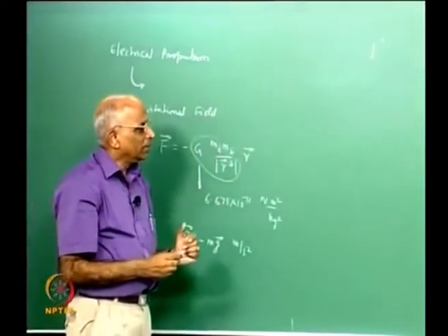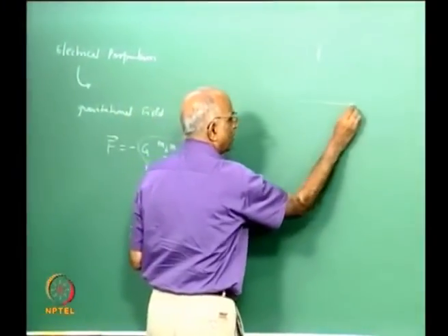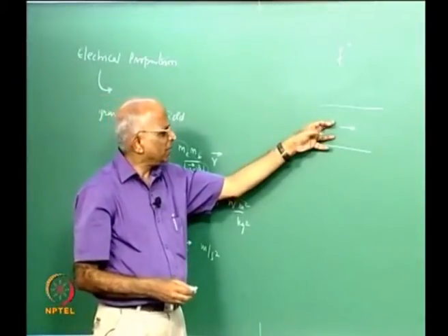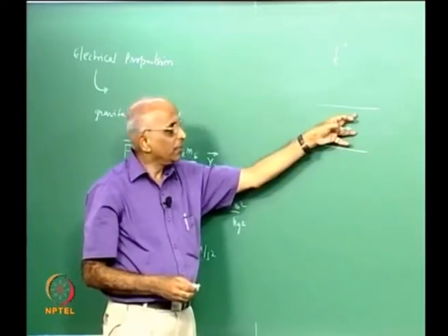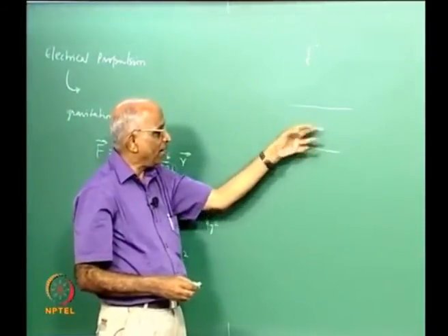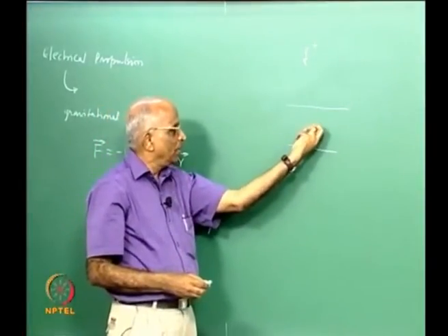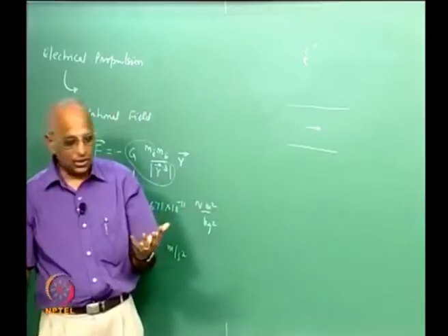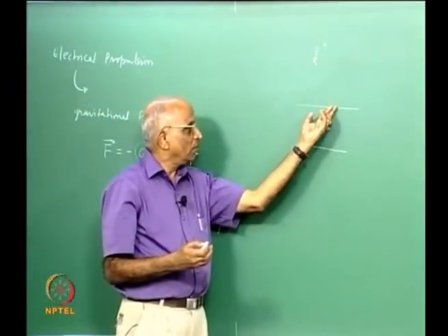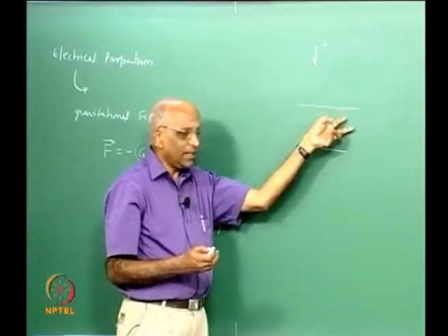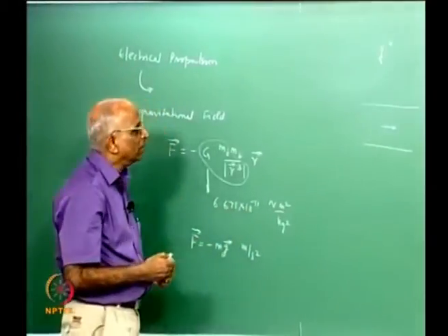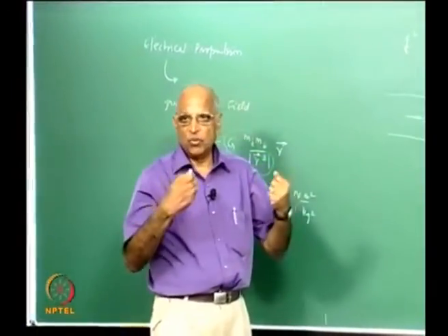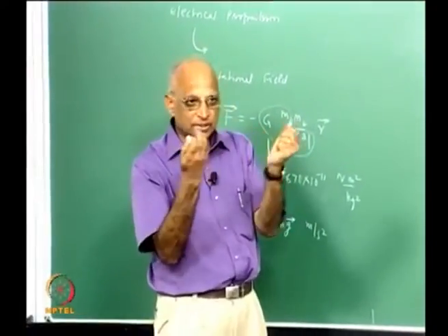In fact, we must remember the charge whenever we have, maybe, a tube containing oxygen gas. If the oxygen gas is very dry and is pumped at high velocity through a particular tube, it is quite possible that since the gas is dry and the oxygen consists of atoms which are electrically neutral, by the rubbing action on the wall I could even ionize it, or give some charge to the oxygen. It is also possible that the surface could become charged because it is getting conducted, and I could get a spark in this, and these are things we have to keep in mind. Therefore, let us not get into those details. All of us know that in a dry climate, if we wear a nylon shirt and we remove it, sometimes it is charged and we hear some discharge taking place.